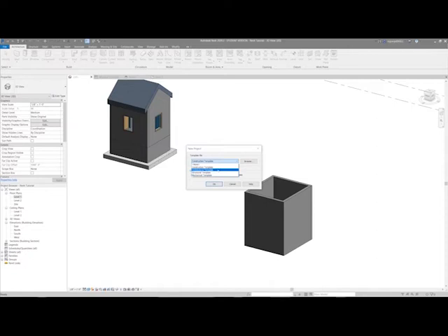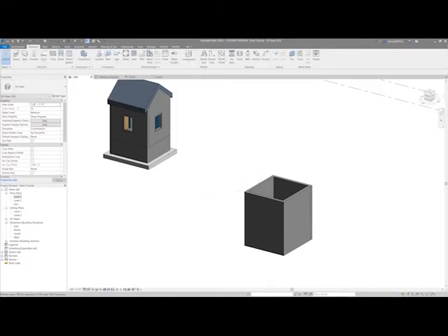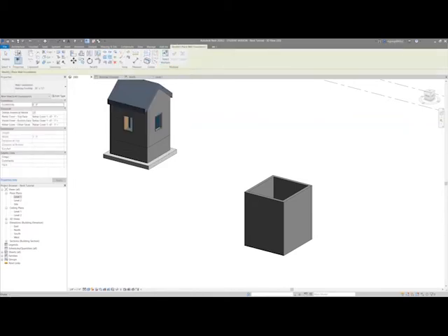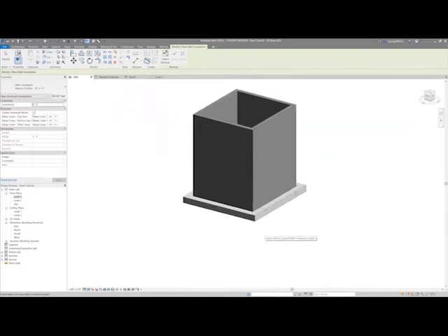So naturally, we're in architecture. So to get the structural stuff, you have to go in that tab, and then say structural wall foundation, find that. And often it lets you just highlight the walls. And then just like that.